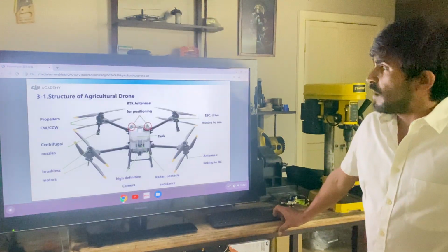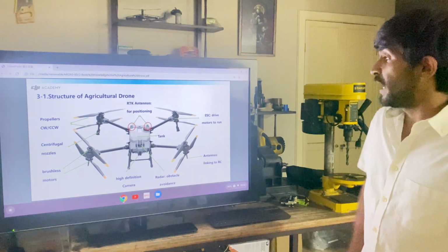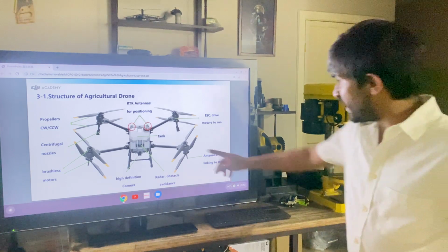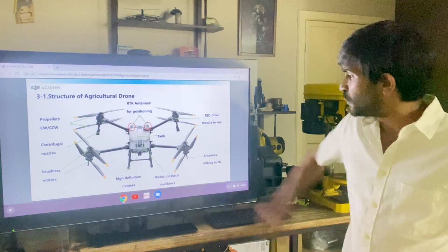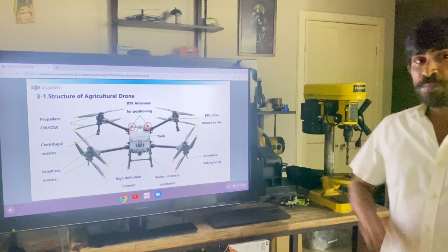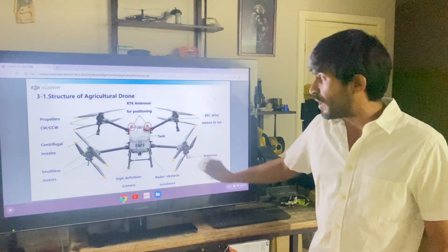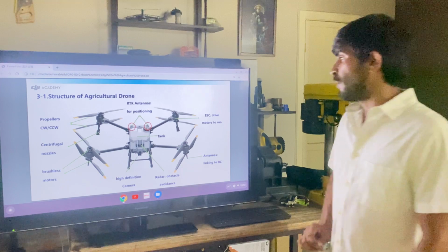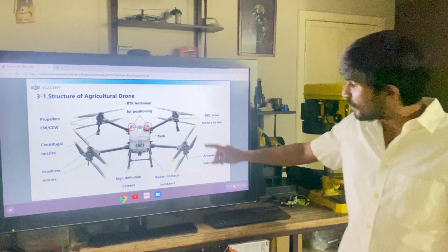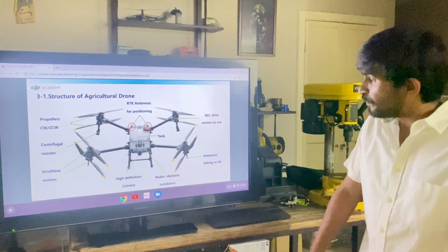Let's talk about the aircraft. This is the DJI Agras T40. It's a very significant aircraft. What's different from previous models is that we have coaxial motors, so we have one motor on top and one motor on the bottom. What's very important to remember is that the propellers are not the same on the top and the bottom. They're different. We have to be very careful about that. You can see the marks. The ones on the top have solid marks, and the ones on the bottom have a black strip on the orange marks.